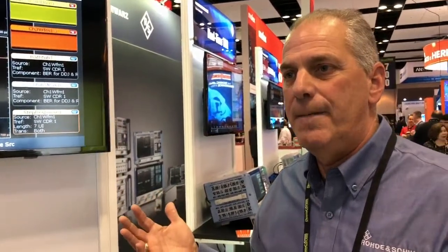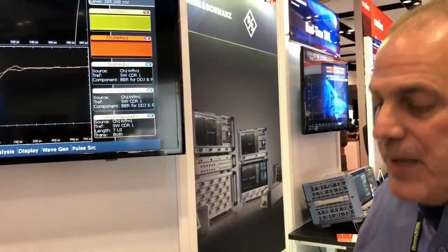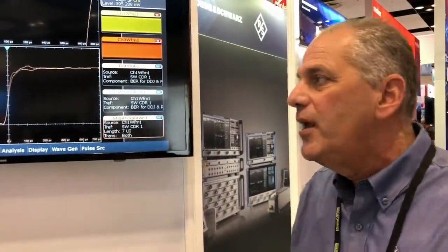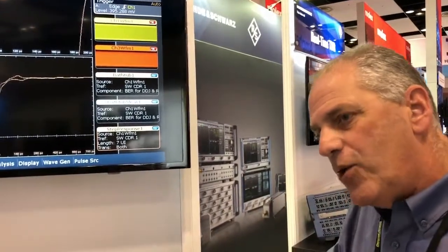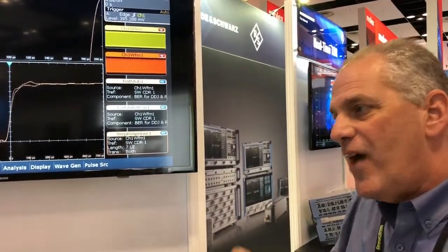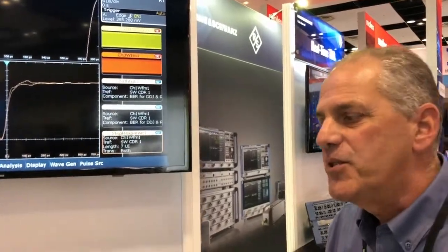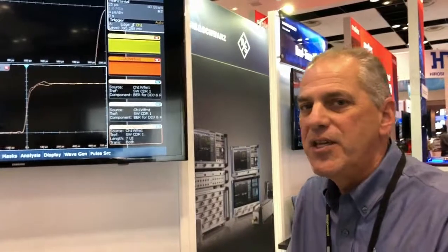The other cool thing is, now that I have this step response, if I have an ISI problem, I can usually see it in there as a discontinuity. Oh, I must have an impedance mismatch or a bad solder joint. We can even get into the chip ball grid array, because I'm just measuring the signal coming out, and it gives me all the information going all the way back into the chip die. So if I have a packaging problem, I would probably see it in that measurement as well. This is a new approach, but we think it's pretty exciting and powerful, and it gives a lot of insight.